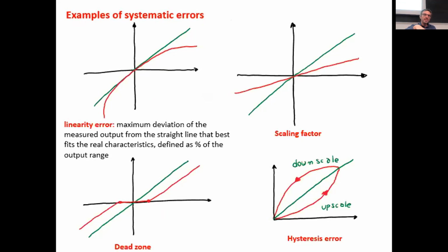Normally the hysteresis disappears whenever you are doing very slow motions. But if you go very fast, with an elastic element, it appears. Another example is the magnetic field in a ferromagnetic material that you magnetize and demagnetize, and you have this magnetic hysteresis, and it's strongly nonlinear. We don't like it. If you have it, you really have problems.